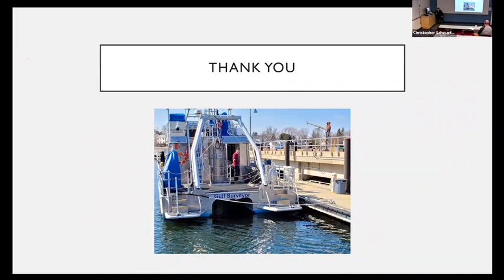The trusted community bathymetry system differs from a volunteer geographic information or a crowdsourced bathymetry system, in that it still goes ahead and logs whatever depth data is available on the vessel's network, but it captures that data using a data logger that has been specifically developed to do that in an efficient way and with as little latency as possible. And it pairs that with a GNSS antenna and receiver combination that is capable of navigating the system very precisely during data collection.